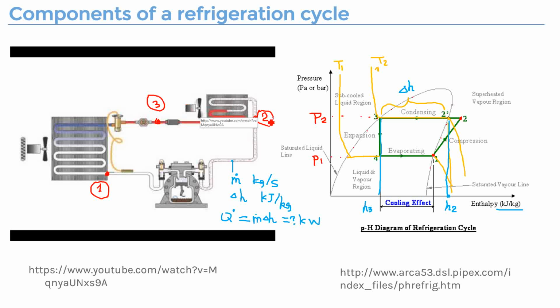So from point 2 to point 3, constant pressure, very easy to find where the points are, because you just draw a horizontal line from point 2. And when it gets across the saturated liquid line, it is the ideal state we want. So we say we find this state.